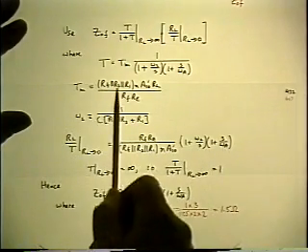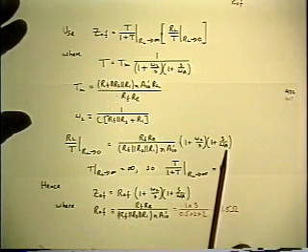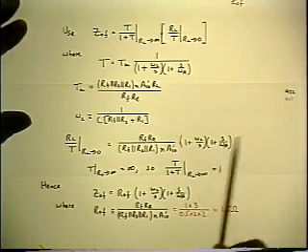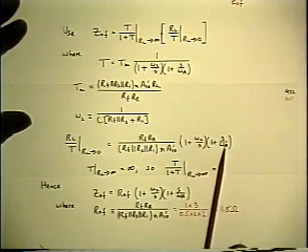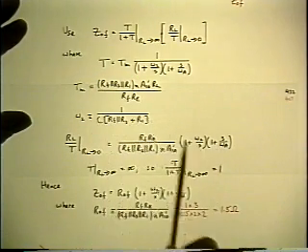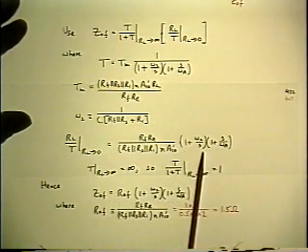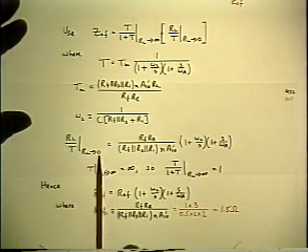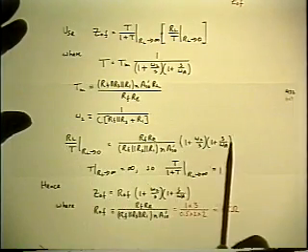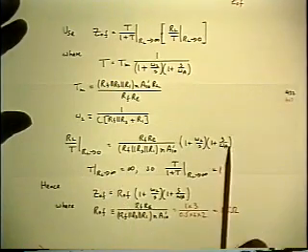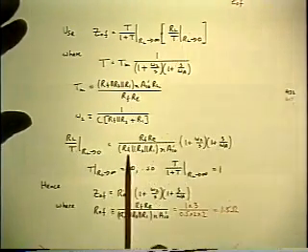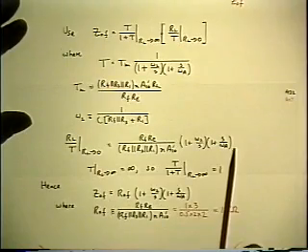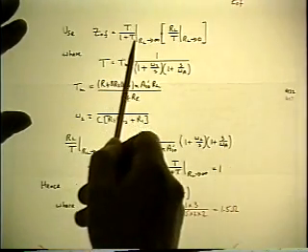And I look at the 2 poles, and the omega A does not contain RL because it was a fixed parameter to begin with, and the omega 2 does not contain RL either. So there's nothing left in that expression that has RL in it, so taking the limit doesn't make any difference. So that's all you get for the square bracket. This is the result. Now you work on the other factor.